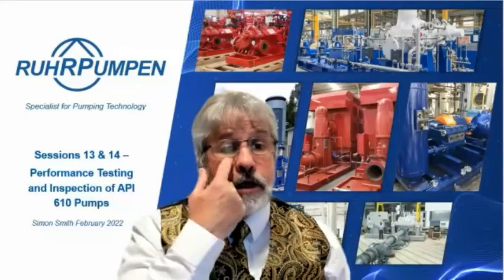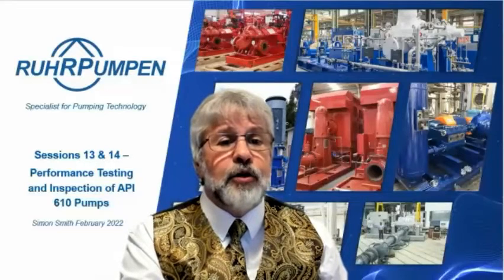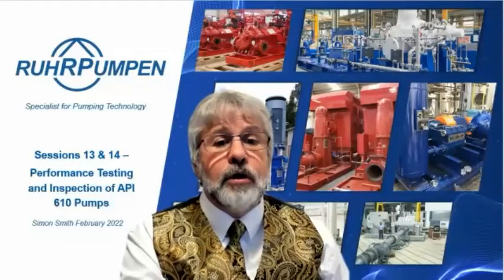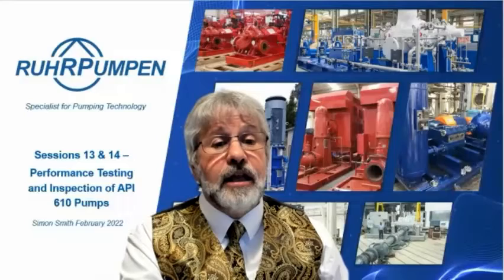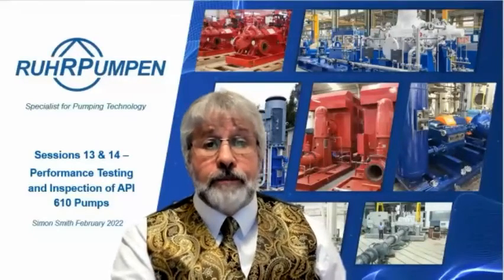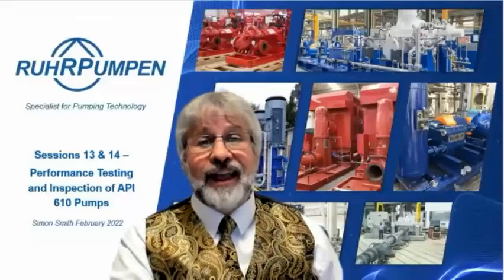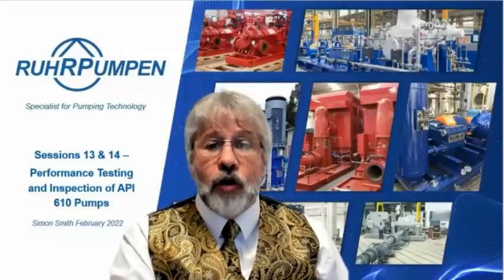David Fairhead says, for smaller pumps, do you typically package everything on the base plate in your pump facility? If so, would this make the complete unit test easier to carry out? For example, you can install the skid on the test stand. Well, we do always assemble the complete pump and motor and seal flush piping on the stand.